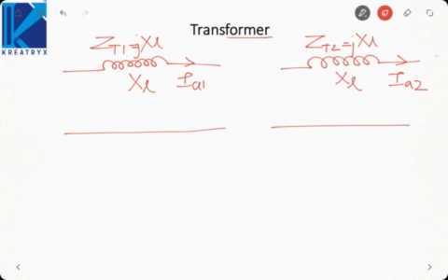This will be IA2. But in the case of zero sequence current, as we derived, zero sequence current can only flow in the lines of the star connection with grounded neutral, or zero sequence currents can flow in the delta winding phase but not in the line. We derived that the line current can only contain zero sequence component in case the connection is star with a grounded neutral. Otherwise, it can only exist in phase of the delta. That means presence of the zero sequence currents depends on the connection of the transformer. So the circuit will change based on the different types of connections of the transformer.